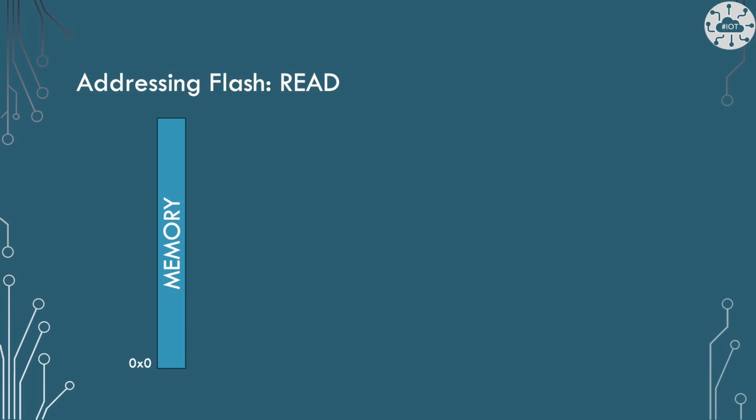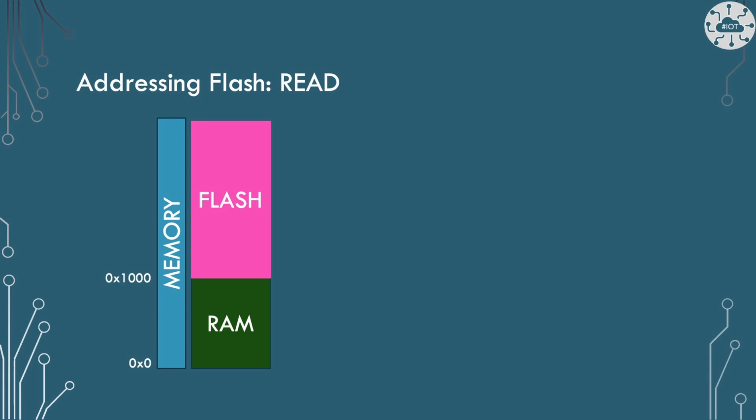So how do we look at the flash? Where does it sit? How does it occupy our Pico? Well, it's actually just mapped into memory. So the flash is just a block of memory that sits above RAM. It's actually at address hex 10000000 in memory, but you generally access that using the definition XIP_BASE.